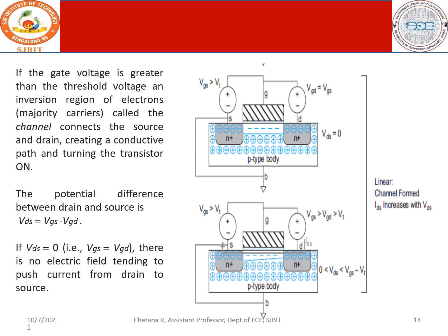And next, once you have the positive gate voltage greater than the threshold voltage, slightly apply a little drain voltage. What happens is there are positive ions at the drain junction, and slightly the region gets depleted here.